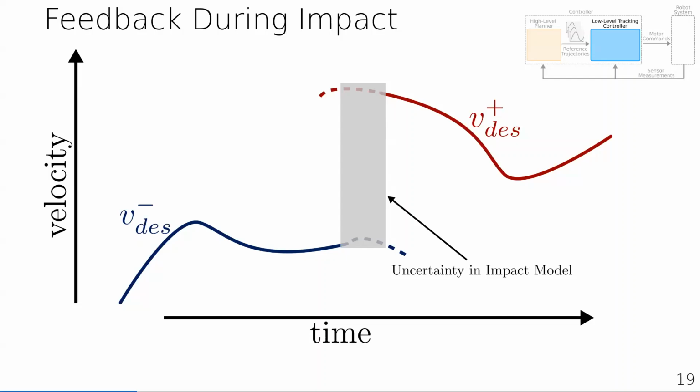Because, as you mentioned, imagine that you have an actuator that has some mechanical compliance. Then maybe you don't need to be that precise, because the mechanical compliance will be absorbing the impacts. So this seems to be applicable only to robots that are very stiff or that don't have such mechanical compliance or capability of absorbing impacts, such that your control is simpler. I was wondering, would you still need something like this if you had a robot with better capabilities in terms of being more compliant with the environment, where the actuators actually absorb these impacts?